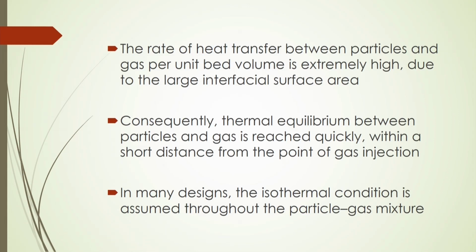Consequently, you can say that there will be a thermal equilibrium. Now, this thermal equilibrium between the particle and the gas is reached very fast, within a short distance from the point of gas supply. So, that is why you will see rapid thermal equilibrium within a short distance from the point of gas injection.